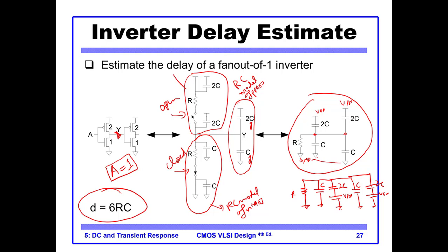Just consider an input configuration. For example, I consider an input configuration of 1. You can consider an input configuration of 0, but it may give a different delay. So you always have to consider the one which is maximum, which is the worst case.